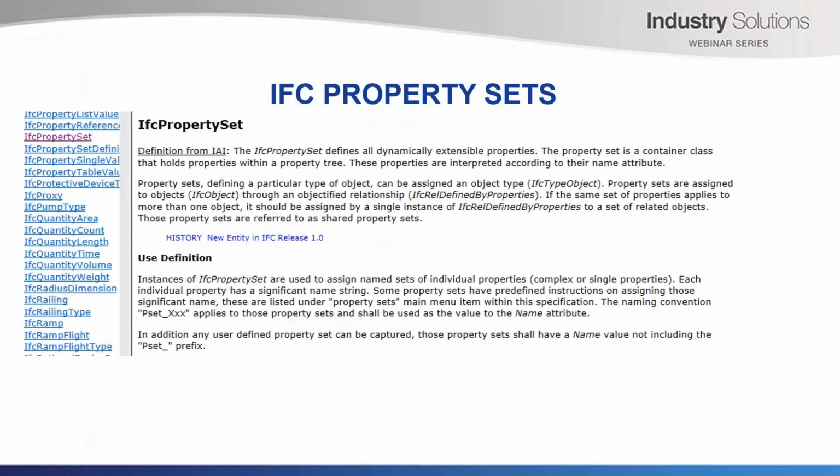And there are very special things called P sets. They're a very special attribute property set which is defined totally by the IFC consortium, and so it says exactly what the names of things are in this P set, what the values are, and what the definition is. And for most of the elements that we're going to see, they then can have a P set that goes with it. So that's all well defined in advance.